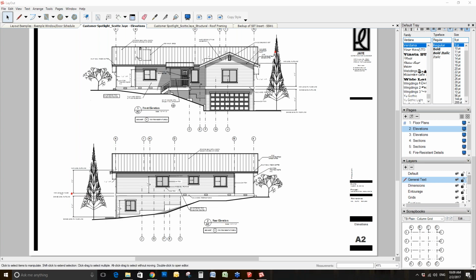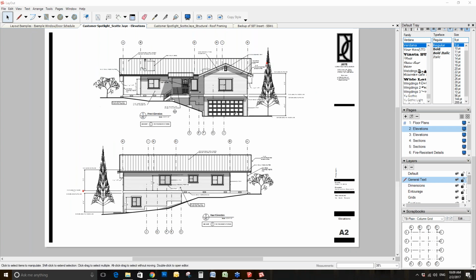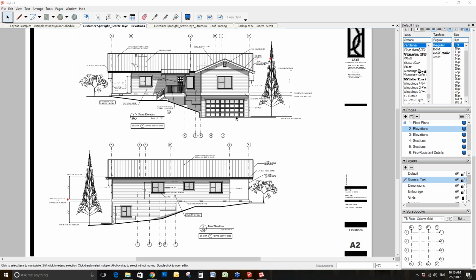One question is, so previously, before SketchUp Pro 2017, if you're working and spending all your time setting up your line weights and your drawings and your hatching in layout, then you needed to export to DWG so you could consult with your consultants, etc. The output was not great, and that's been one of the vast improvements of SketchUp Pro 2017, is that now your layout drawings, everything you do, your line work, your line styles, hatching, masks, everything, you can then export into a DWG format, and it will be exactly the same as what you've done in layout.